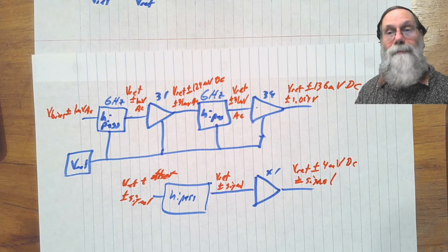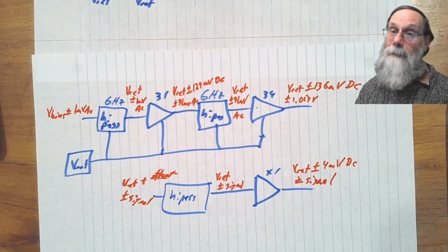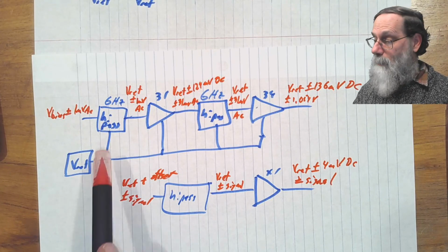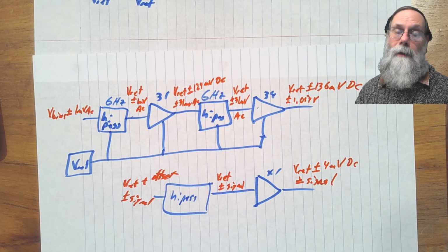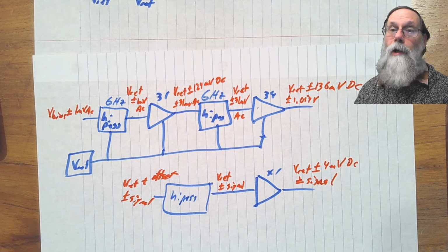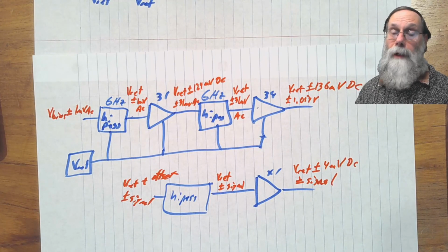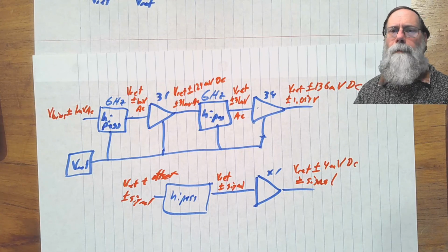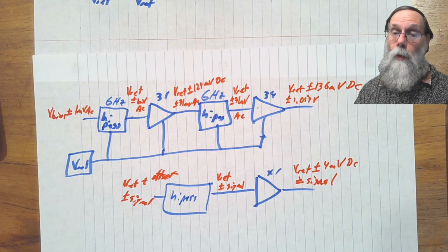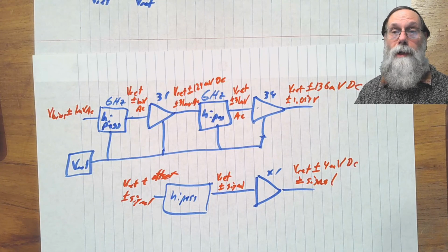Because if you amplify that input offset without doing something to remove the offset at the intermediate stages, you can end up with your final DC offset being large enough that you clip or even lose your signal entirely. Okay. There are undoubtedly other reasons why someone might want to use multi-stage amplifiers, but these are the important ones for this course.